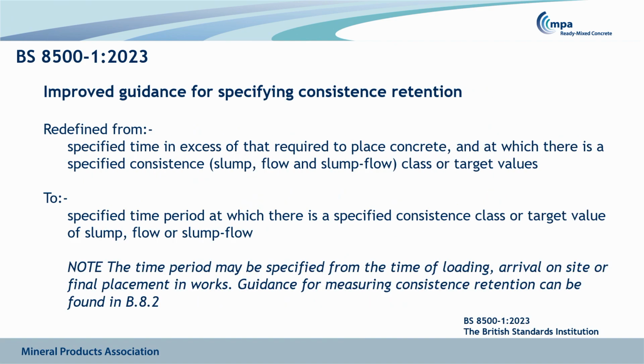We're seeing, certainly concrete suppliers are seeing, an increased requirement for consistent retention of concrete, where we need concrete to remain live and open for up to several hours after production. And so the guidance has been improved slightly. The definition is pretty much the same. Instead of saying specified time, we've said specified time period, and that's because there are pedants out there who, if you say specify a time, will say 12 o'clock and not 2 hours.